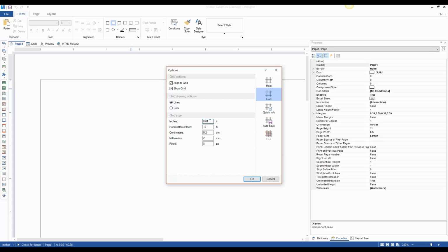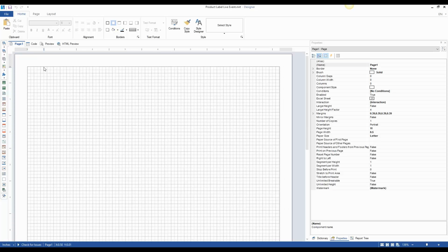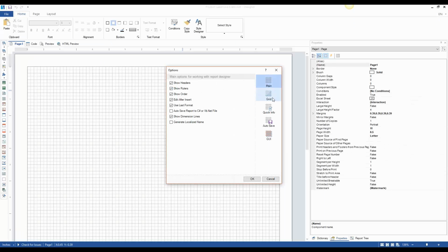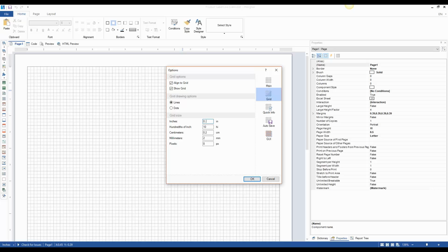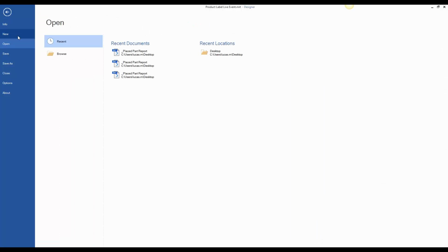One thing I do is change this option here to a 1/1000th of an inch versus 100th. By default it comes in at 100th, and what we're going to see here is that our grid is slightly bigger than what I had it set to previously. While this is good and makes placing objects very easy, it doesn't always allow the fine tuning of how you want these objects placed, and a lot of times you want to be able to fine tune it just right. So I come in here to the grid and change that to give me a smaller grid size. That helps me fine-tune my placement and get it exactly how I want it. I'm also a little bit OCD about it, so that might not be something you need to do.